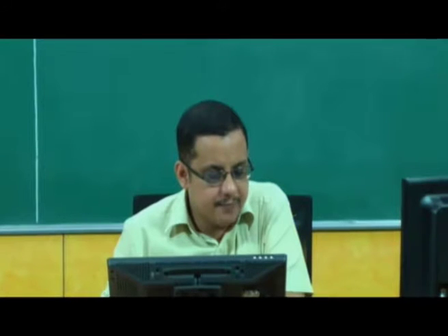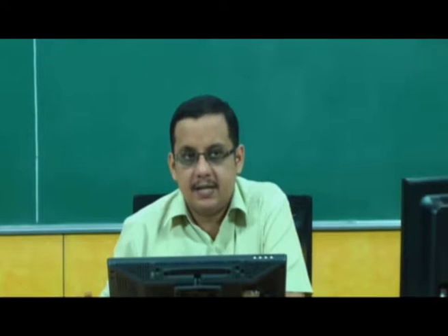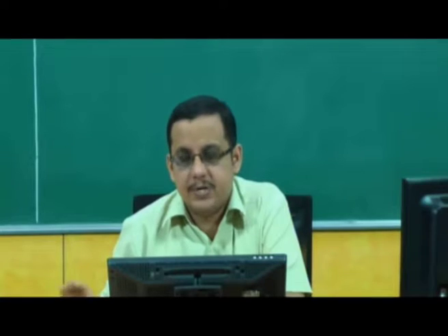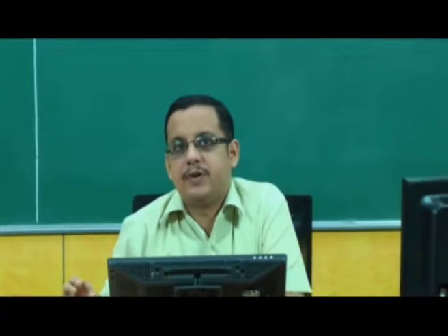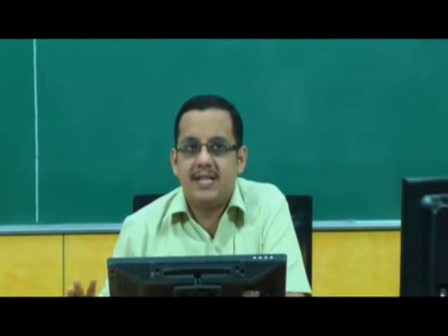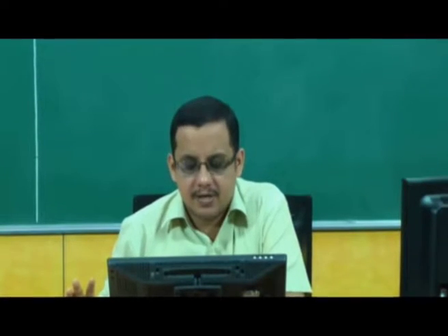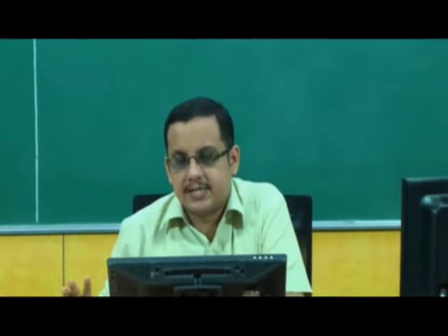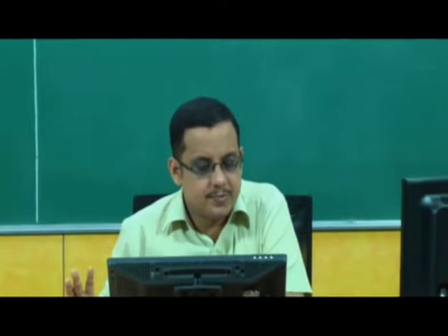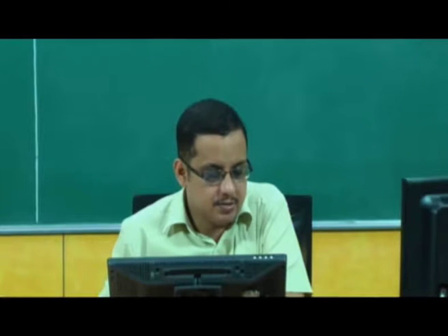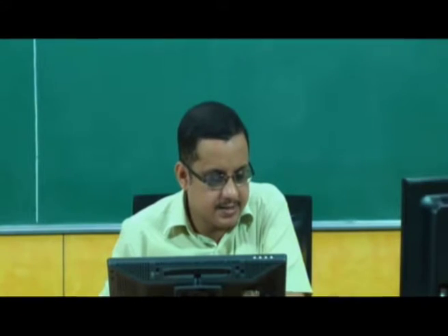KECP is asking if pitch point is not fixed, what about velocity ratio? I exactly said this, the same thing. If pitch point is not fixed, velocity ratio is not going to be fixed. If pitch point moves during the process of engagement, then the velocity ratio will also move. This is exactly what is called the fundamental law of gearing. Because of the fundamental law of gearing, it is demanded that if velocity ratio has to be fixed, then the pitch point has to be fixed. If pitch point does not remain fixed, velocity ratio will not be fixed. So that answers the question from KECP.